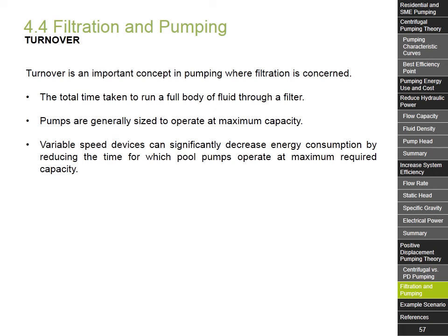Turnover is an important concept in pumping where filtration is concerned. It refers to the total time taken to run a full body of fluid through a filter. This is important for two reasons. Firstly, pumps that are required to perform turnovers are generally sized to operate at the maximum capacity required to achieve this. This is often significantly over the required capacity for regular operation.